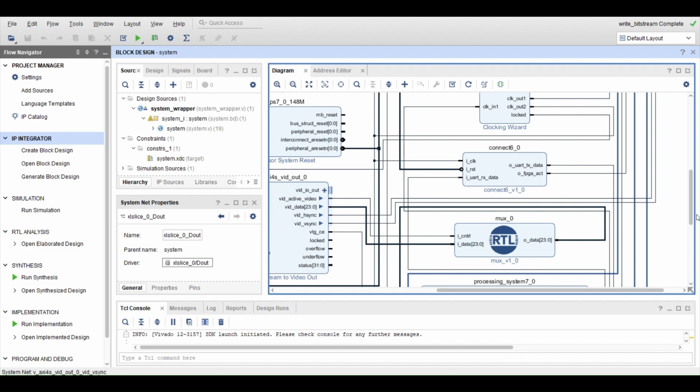The processor sends the player's move coordinates over UART. The FPGA AI computes the best response and sends back its move coordinates. This offloads the AI computation entirely to dedicated hardware logic.